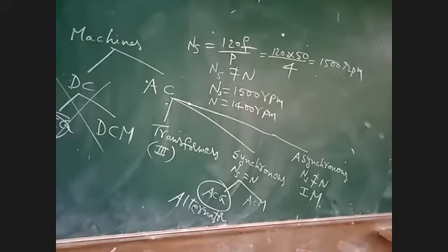So while designing, it is 1500 rpm, but when you run it at home, it may not be at 1500 rpm. It will run at 1300 rpm, it will run at 1000 rpm. There is a difference between the speeds. n is the actual speed in your house, ns is the designer speed. If both are not equal, it is called an induction machine. In your house we are only using induction machines, that is asynchronous machines, not synchronous machines, because we want variable speeds.